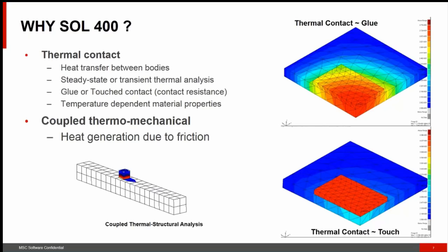You can even perform this type of analysis with structures that have different meshes using a restart procedure. And MSC Nastran allows the temperatures to be interpolated from a different mesh model, as I said. This is a useful tool that's available in solution 400.